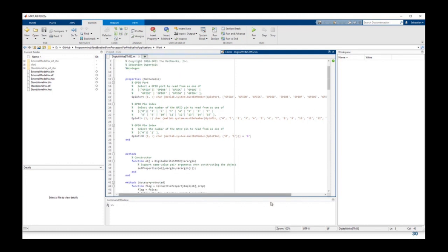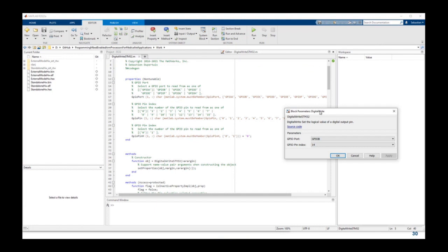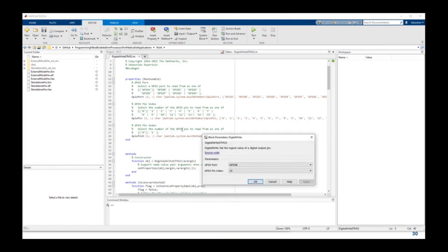And then perhaps I can just open the mask here again. Yes, you see, now you have the mask, and you can see that the properties that are non-tunable within this class, like GPIO port and GPIO pin, you can retrieve them there. All that you write here will be reused and will be displayed in the mask. For example, if I take a GPIO port, I click here, and you can see that I have already populated the GPIO ports that I am allowing to use. For example, from A to F, I think, even to H, yes. So here you can just select that.